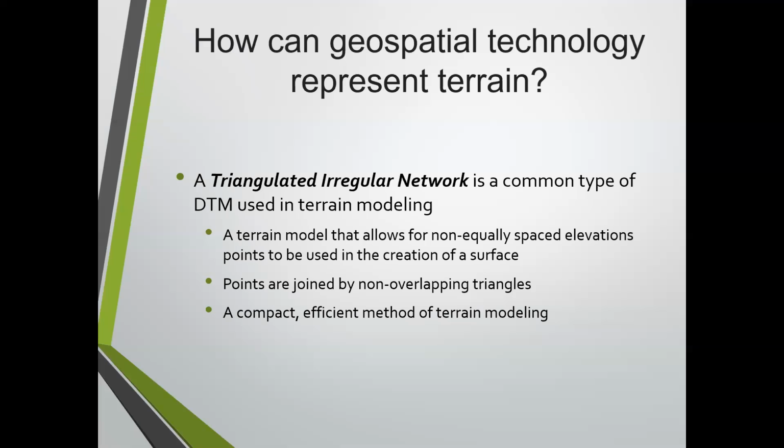You guys know that. One of the things I'm sure you've all experienced is where you'll get one blown point, where somebody maybe raised the rod for one shot and then forgot to change it back to the normal setting in the data collector. So you have one or two shots that are higher or lower than they should be. So you'll get what I call an island or a hole that develops. You can go in and either fix that point if you know what the change was, or you can just zip the point out so it recontours or recalculates. So yeah, there are a lot of great tools available in any of our software to do that.